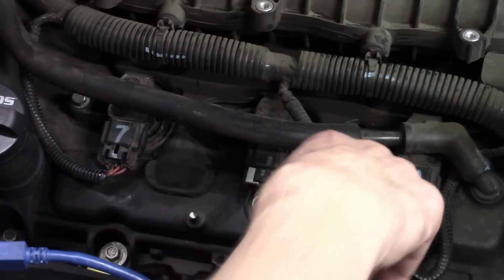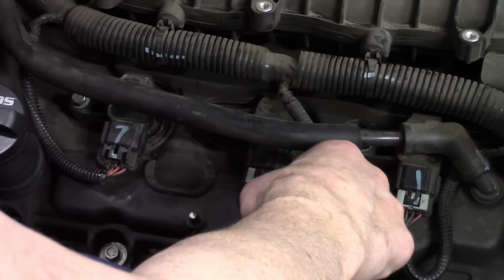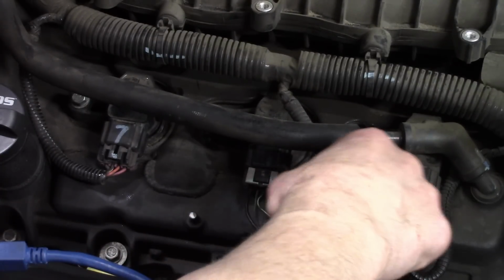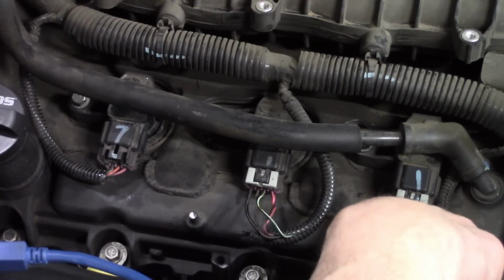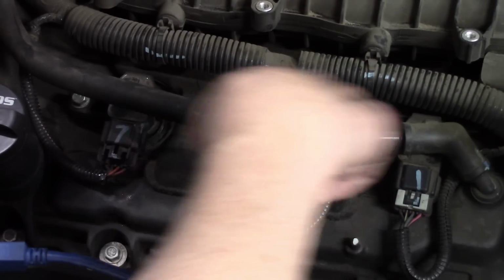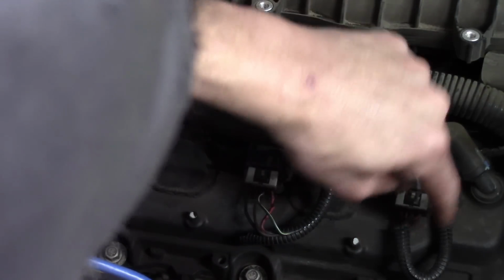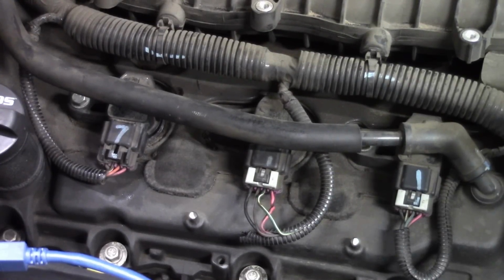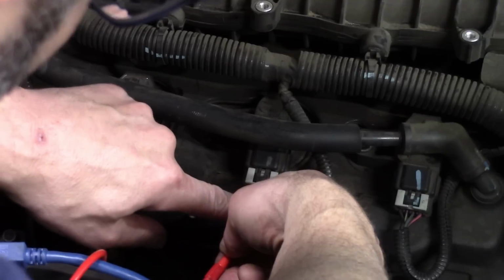All right, so we'll access this one here so it's a little bit easier. Let's see, all of these have a pink and black. We know all of them had a brown and white. This right here is a green with a white. I don't know what color that is, but this one here is a red. So this wire here is the one that's different. This third wire over is different on every one of these. That is going to be our signal input, a signal in, positive voltage from the computer. I am calling this a positive side switching. I don't care because it's easy.